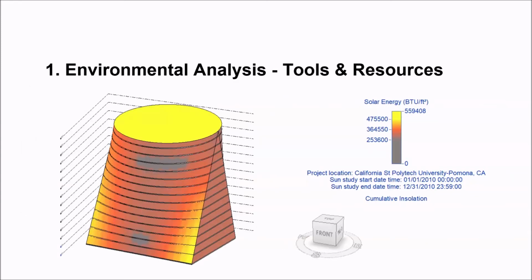The results in some ways tell a similar story of what we learned with the lighting analysis, but the information is different and serves a different purpose. While I've run this analysis on the full mass, you would likely constrain your analysis to areas you would consider putting PV. The roof, if not dedicated for mechanical or a roof garden, is a common spot and clearly the best spot according to this analysis.